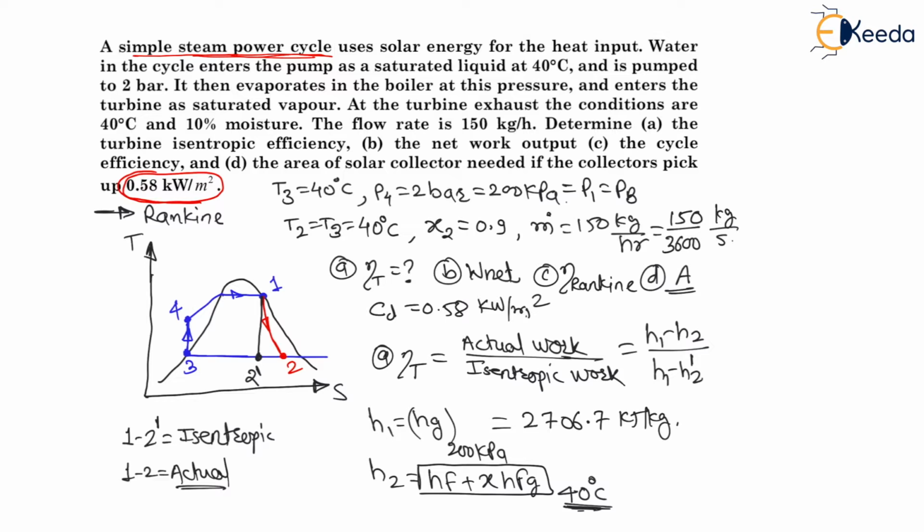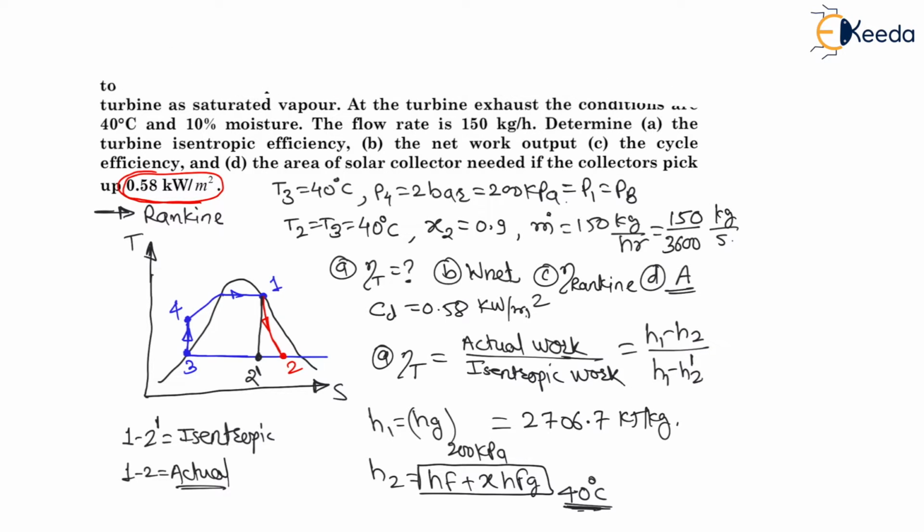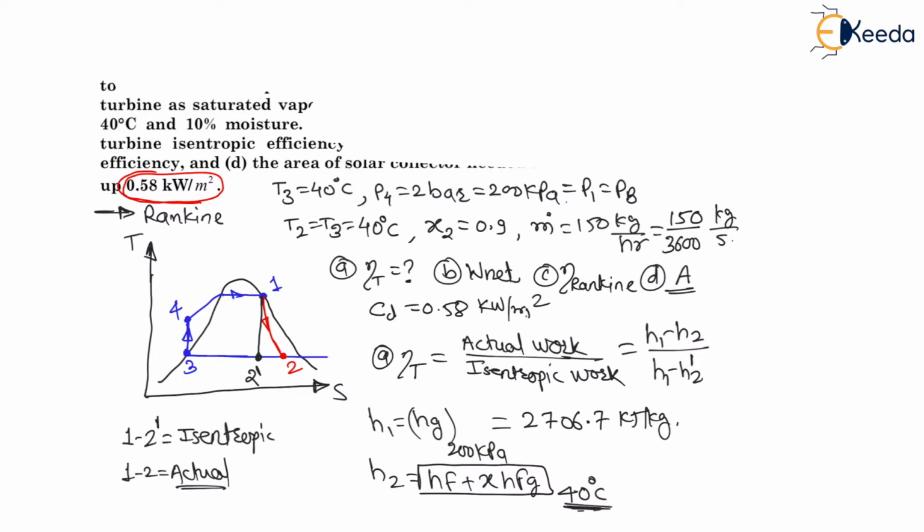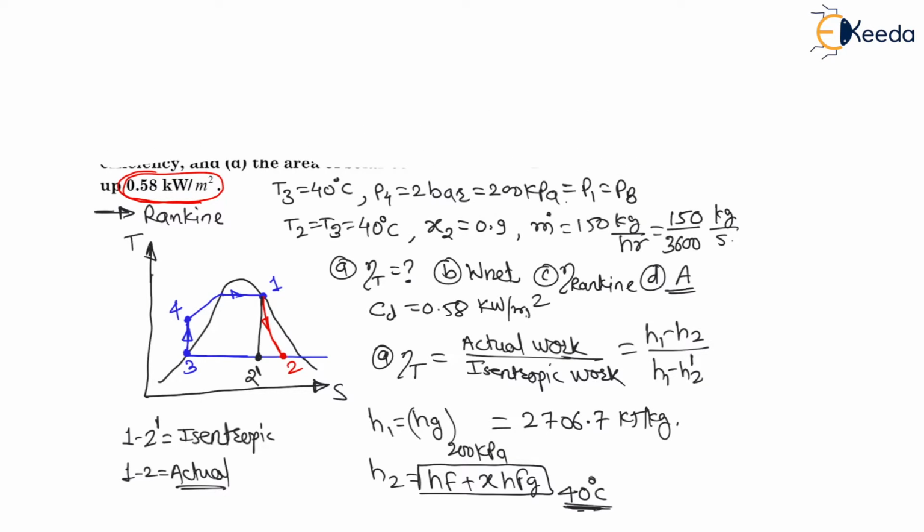degrees Celsius. Now here I am deleting the question so that we will get sufficient space for the solution, because all the given data we have written, so there is no need of the question now. Now my dear students, from the steam table at 40 degrees Celsius, I will get these values. This hf value I will find. Here I am writing these values which I am looking at. At 40 degrees Celsius, I am getting the saturation pressure,